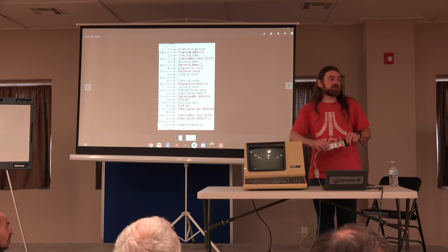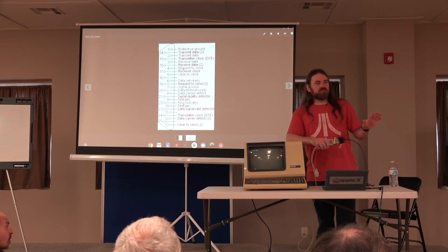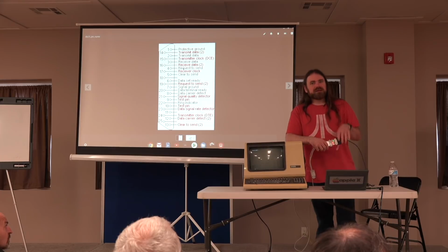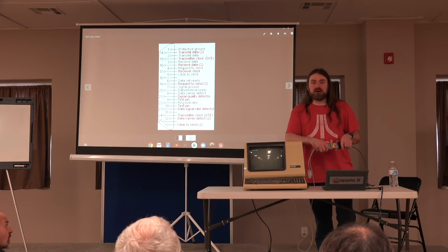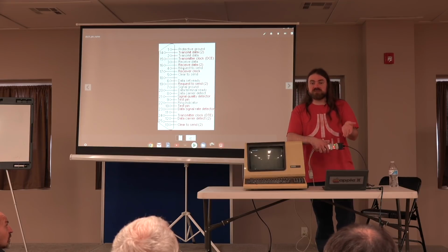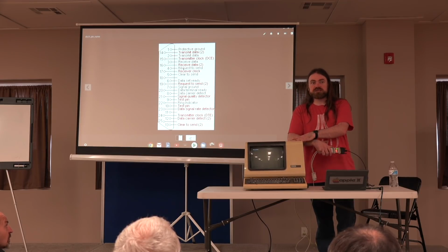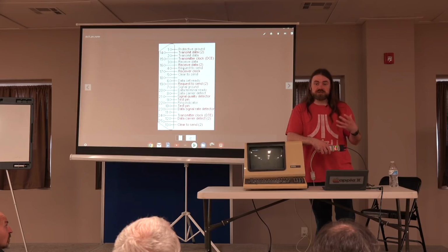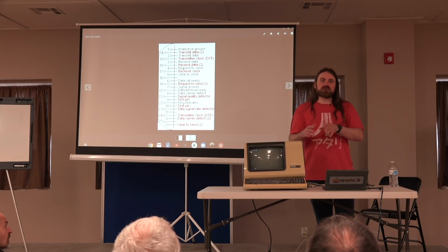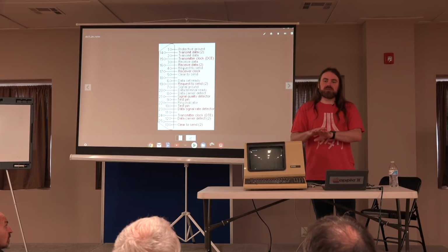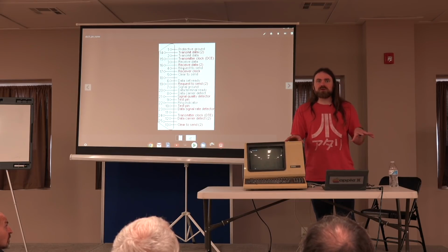Well, it depends on what you're connecting to. Oh, sorry, I have to repeat the question. He's asking what baud rate to operate at. First, I should mention what baud rate is: the speed that the computer devices are transmitting or receiving. The traditional baud rate of something like a teletype machine is 110 baud. And that's your standard, the lowest common denominator, 110 baud. Modems, 110 or 300 for the very early stuff.